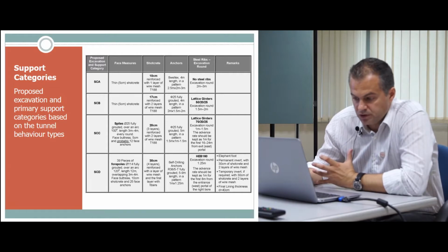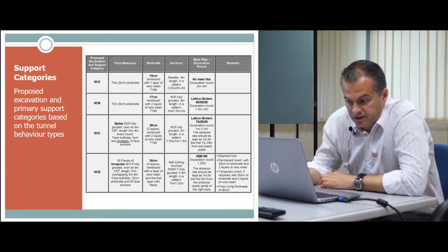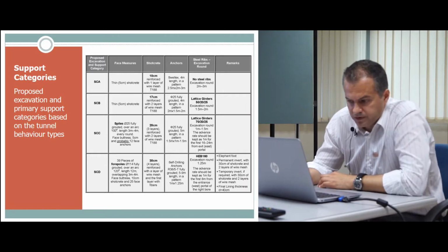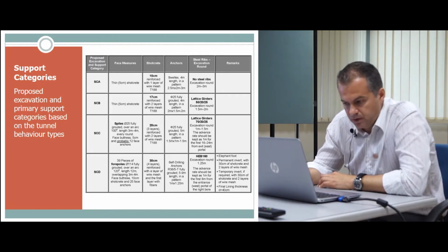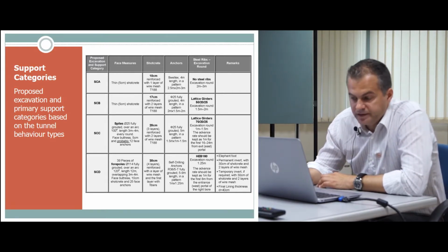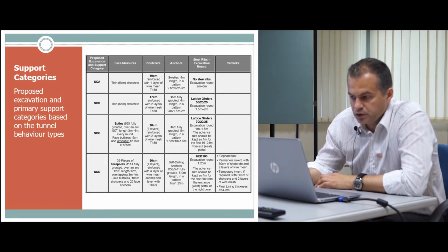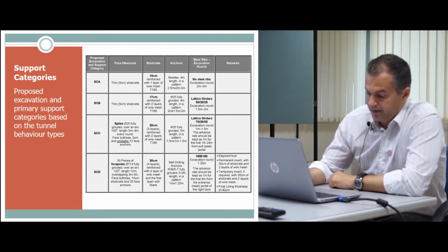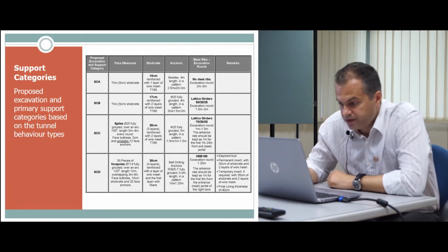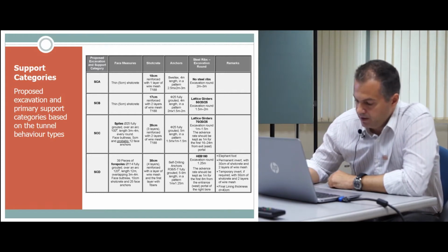The last one, which is shear strain failure and isotropic failure of the rock mass, here you need some forepoles and face buttresses of shotcrete and face anchors to keep your face safe, and thick shotcrete, a more dense pattern of anchors, and heavy steel sets are required here with elephant foot, and a permanent invert may be required for this kind of ground conditions.